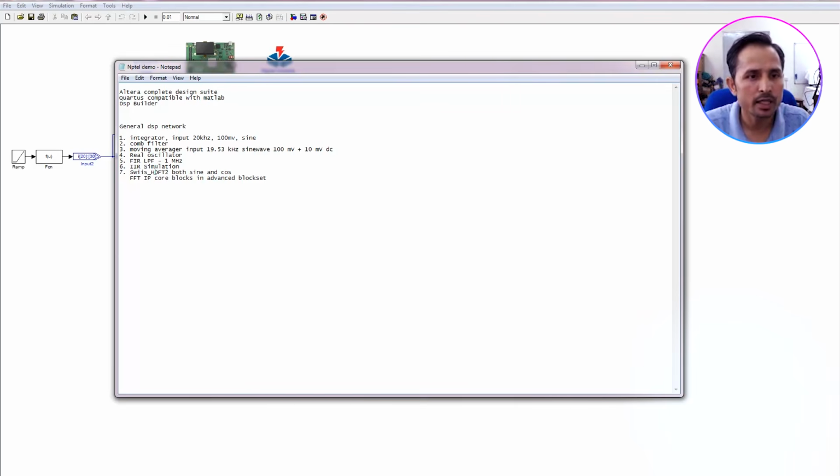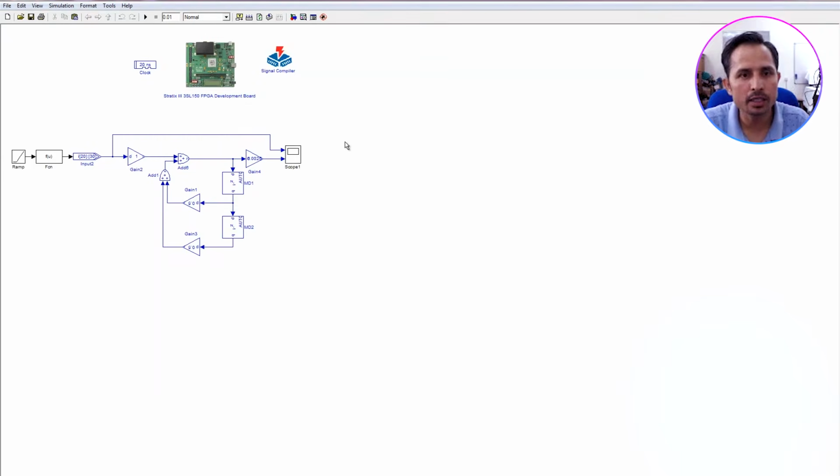Now the HDFT, it has already been taught in the lectures. HDFT is one of the extended versions of the SDFT, which is sliding discrete Fourier transform. HDFT is hopping discrete Fourier transform. I will be giving an input signal, and it should be able to give me the extracted in phase and quadrature phase.